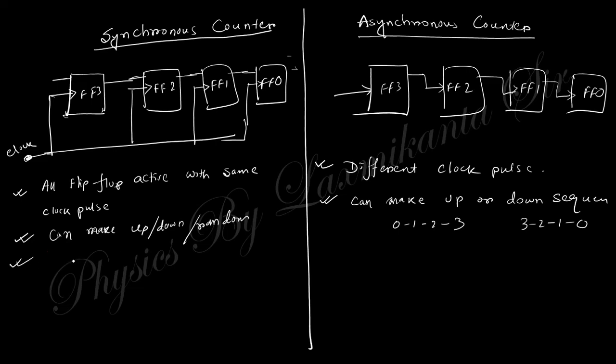In synchronous, since the flip-flops are triggered by a single clock, this is faster. Comparatively, the asynchronous is slower, not very much slower, but comparatively slower. And as the synchronous requires more gates, it is a complex design, while the asynchronous is a comparatively simpler design.